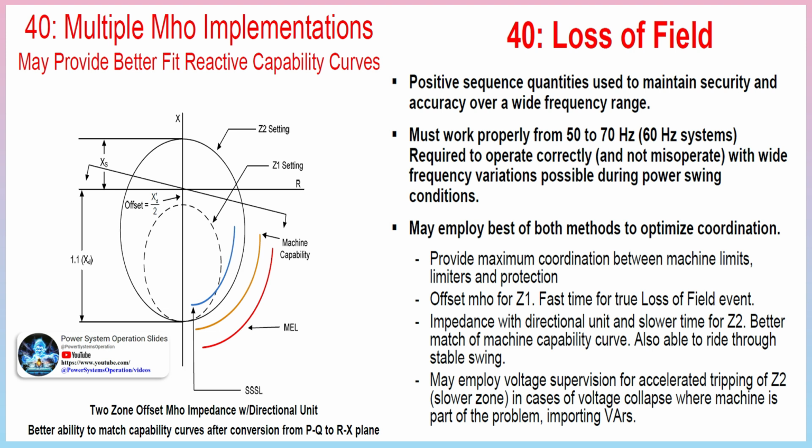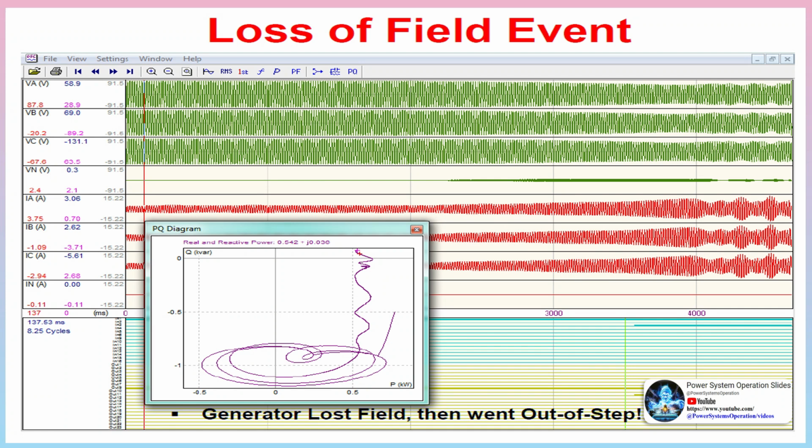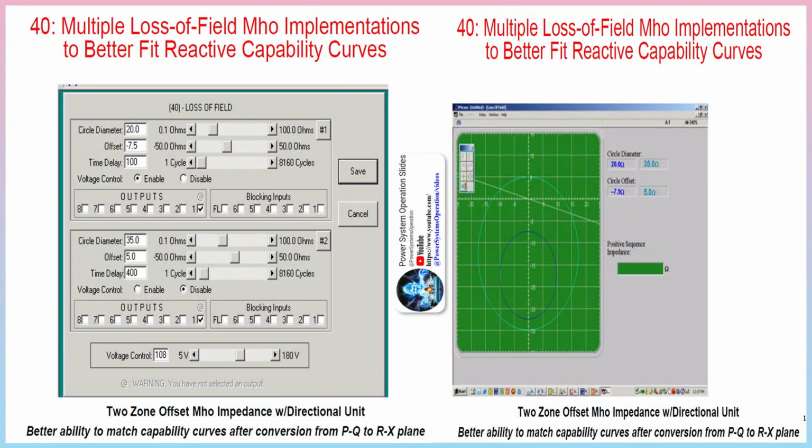Loss of field can adversely affect the generator and the system. Generator effects: synchronous generator becomes induction, slip-induced eddy currents heat rotor surface, high reactive current drawn by generator overloads stator. Power system effects: loss of reactive support, creates a reactive drain, can trigger system area voltage collapse. Generator capability curve, limiting factors are rotor and stator thermal limits. Underexcited limiting factor is stator end iron heat, excitation control setting is coordinated with steady state stability limit. Minimum excitation limiter MEL prevents exciter from reducing the field below SSSL.